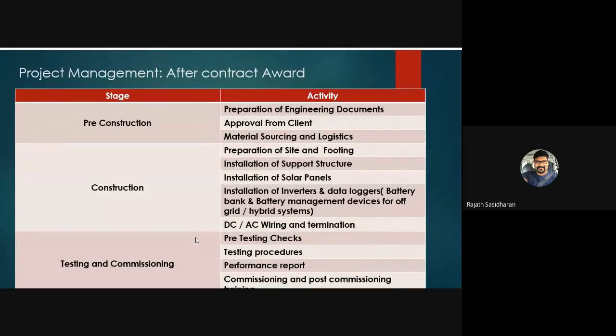So sometimes a different brand panel will have a different dimension, so we don't waste our time in due course. Yeah. So shop drawings are often prepared after material submittal is approved. The shop drawings will come ideally in 3 sets.